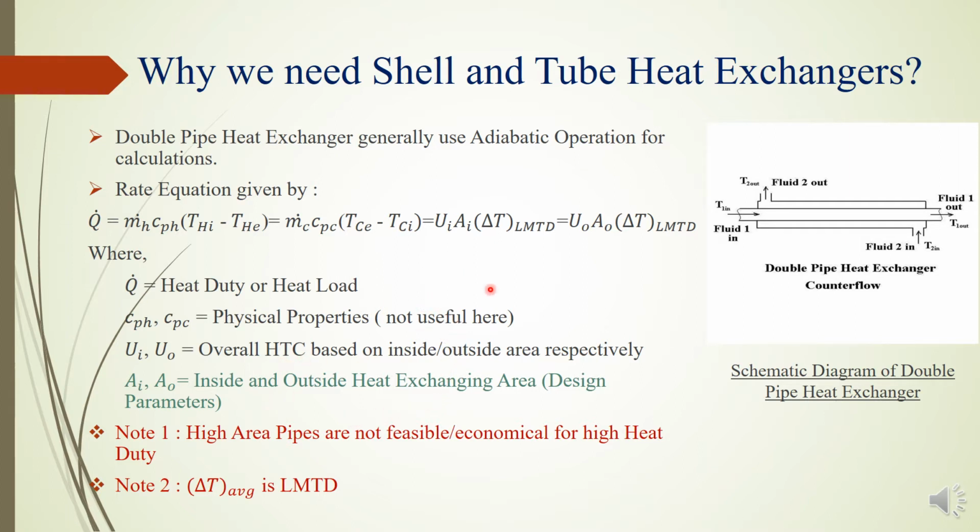Note delta T LMTD. So, what is the importance of LMTD in heat exchangers? LMTD is the logarithmic mean of temperature differences of the fluids at both sides of the heat exchanger. It is introduced because the temperature change across the heat exchanger from the entrance to the exit is not linear. The use of LMTD arises straightforwardly from the analysis of a heat exchanger with constant flow rate and fluid thermal properties.